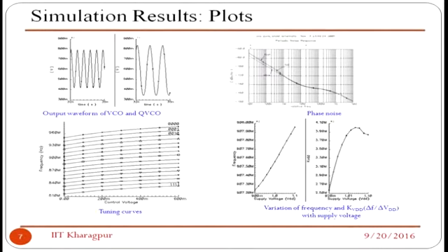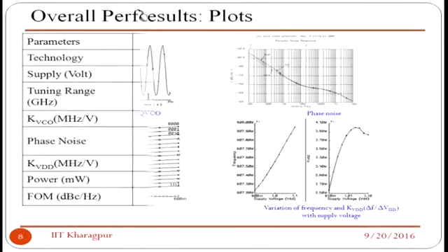That is what I require. I need a very smooth ride over the frequency-voltage tuning. I don't want any sharp rise, which will introduce a huge amount of noise in the system and instability. So that's why, by using this capacitor bank with the varactors, you make use of this for a lower KVCO and stable oscillations.